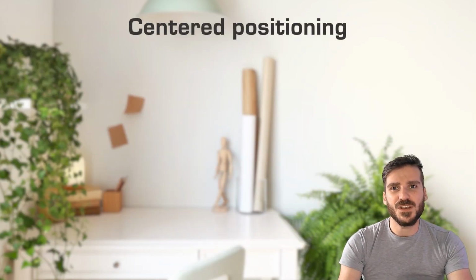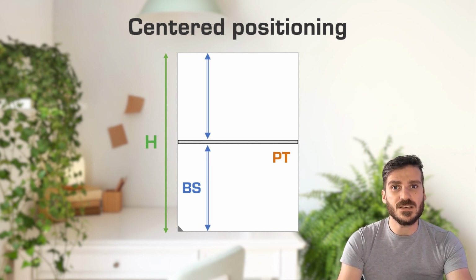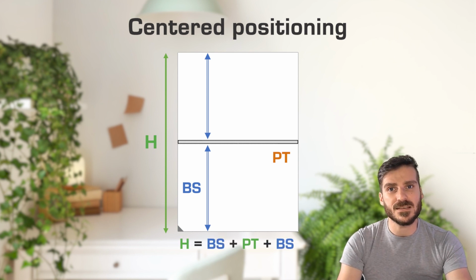For the centered positioning of the shelf, a diagram here can be seen. In green, we have the SWOODBox height dimension, which will be h. Then we can see the panel thickness here, which is called PT, and the distance parameter we just created, bottom space, which is at the bottom, and in case we have a centered positioning, this distance will be the same at the bottom and at the top. So we can see that the height h is equal to bs plus pt plus bs a second time.